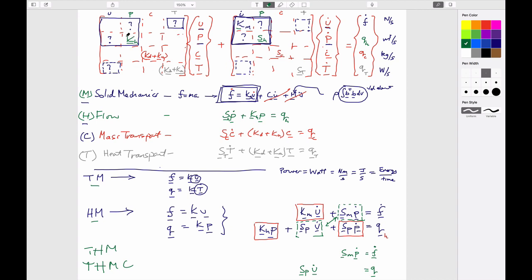If there are changes in material properties, then within this conductance matrix here, and we know that this conductance matrix looks something like the integral of A transpose dA dV, right? We know that these are the shape functions, so those won't change, but this is Darcy's law.